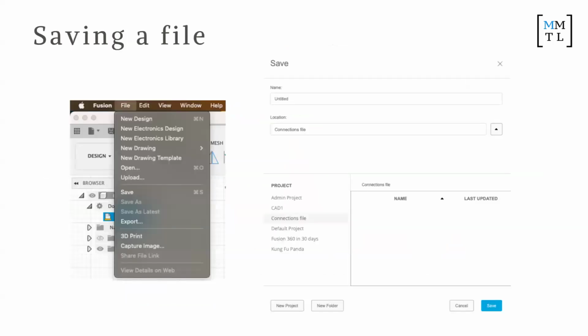So first, if you guys all want to make a new design, go to File, make a new design, and you pop up with the tab within the Fusion program. And you can close the last program, and if you made any sketch, you can save it if you want, but just try and jump on a new program so we're all fresh slate. And the next thing you want to do is save this file right away into a location that you're familiar with. So click save, and then name this as your first CAD session.